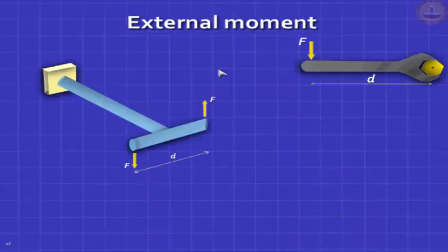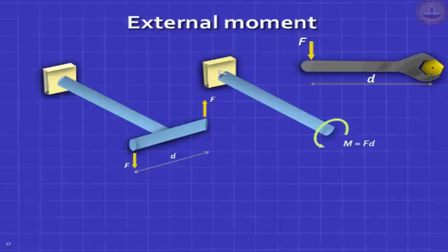Both will cause bending. But often mechanical engineers think of bending in terms of shafts rotating and so on. So you should also know that this is also a moment, okay, but this causes twisting, not bending. You must know the difference. It's outside the scope of this topic, but you should also know that that's also moment, but this is rotation about a longitudinal axis. This is called twisting, and the external moment that you apply, the word is torque.